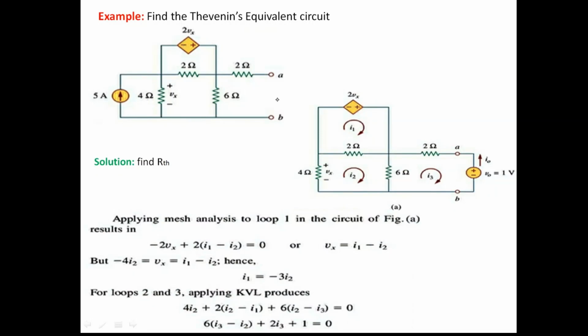So since this circuit contains one dependent source and one independent source, the method 2 which we considered earlier, using the series parallel reduction technique, is not applicable to find RTH since it contains dependent sources. So method 1 you have to apply. Method 1, which we discussed in the last class, is now applied here. So what does our method 1 state? For this circuit, where you want to find the Thevenin's equivalent circuit, there you connect a known voltage source of magnitude 1 volt.